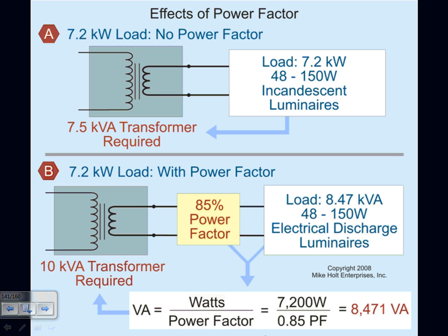So later on, when you guys are in the field, you find, especially lights, you find the watts for the light, and you're going to have a power factor with it. If you don't have a power factor, it's a good assumption to assume the power factor is going to be 0.9. Is it typically on the label? It should be. Or if they don't give you the power factor, they give you the amp and the voltage, so you can figure out the amp. So if this is 1 amp and the voltage is 120, piece of cake. It's 120 volt amp. Yep.